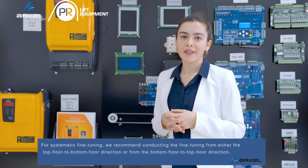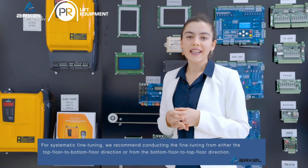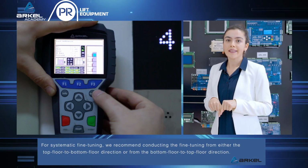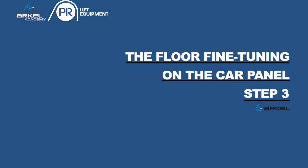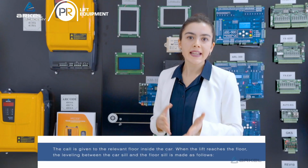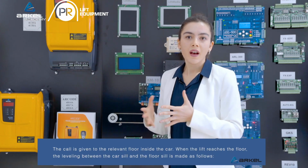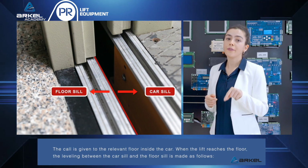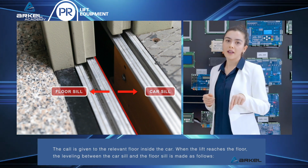For systematic fine-tuning, we recommend conducting the fine-tuning from either the top floor to bottom floor direction or from the bottom floor to top floor direction. The call is given to the relevant floor inside the car. When the lift reaches that floor, the leveling between the car sill and the floor sill is made as follows.